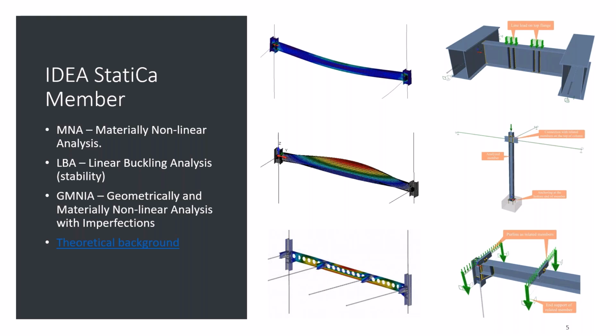So why are we analyzing only one member? Well, that is because we are not using 1D elements or the beam theory. We convert the full model into shell elements, including the focus member that we are analyzing in the application, the connections to the support members, and also all other related members. Imagine if we would like to model the full structure using shell elements. That will take a lot of time, right? So that is why we're focusing on just one portion of the structure.